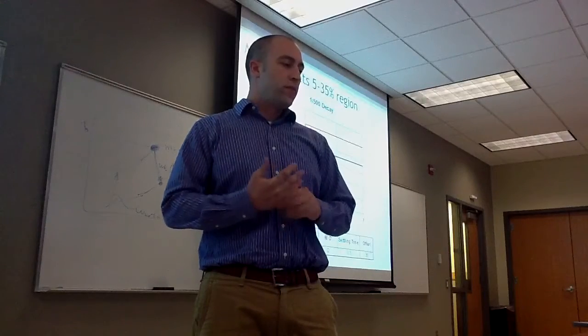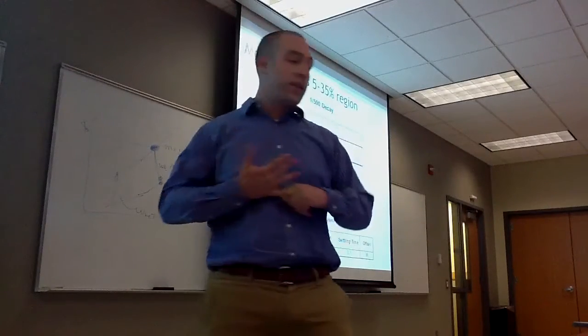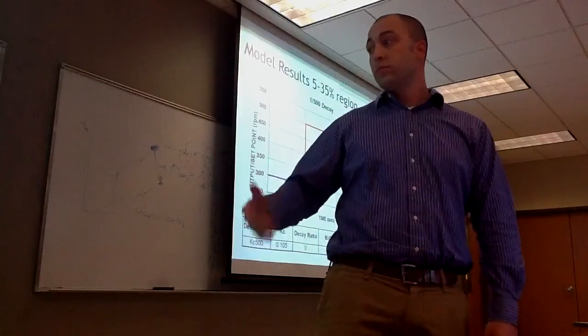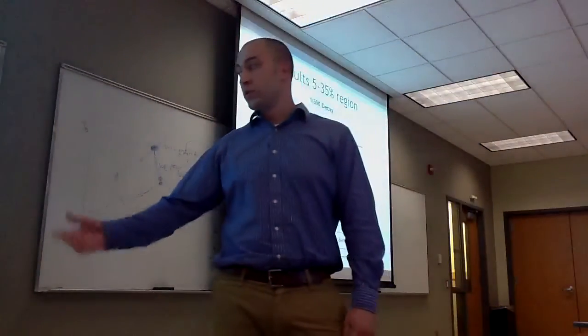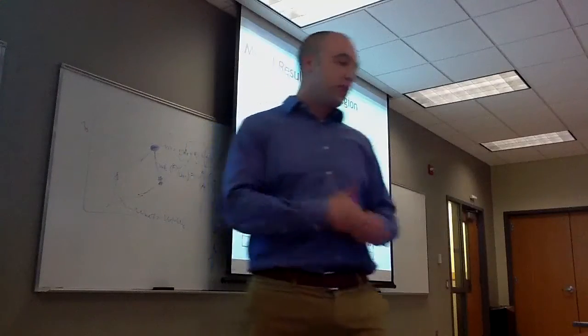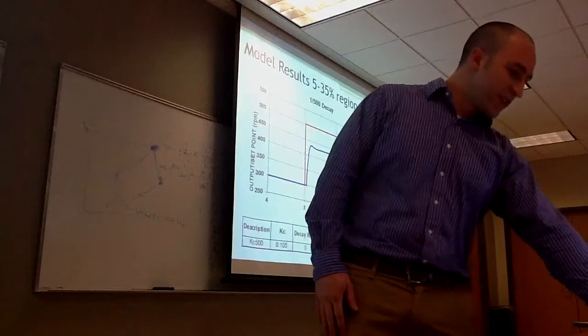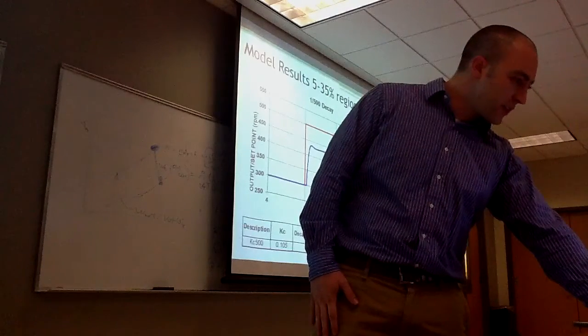Here's the 1/500th decay. You can see it jumps a little bit right after the step, which is oscillatory. Settling time fairly quickly, 0.3 seconds, and an offset of, I got that wrong too, I have to change these. It's supposed to be, I think, 76.